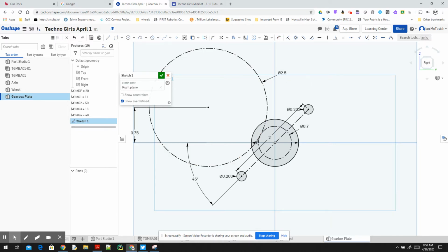You can modify these once you've got things designed. You can play with those values if you want to change them around. So I'm going to now add G3. So gear 3, again, it's a circle and a construction line. Gear 3 is going to be on the same shaft as gear 2. And so I'm going to use the center of gear 2 as my starting point, and click and just hit escape.